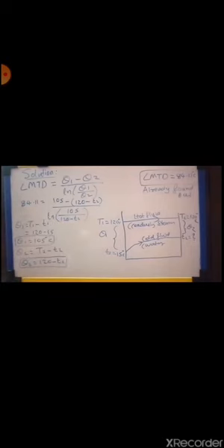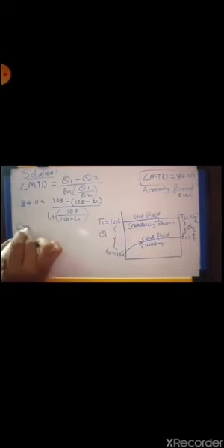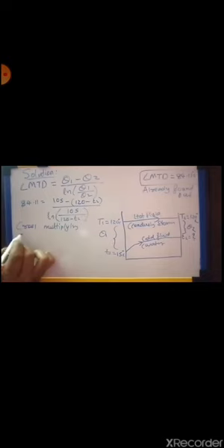Then the next step is cross multiplying. Cross multiplying, we get ln of 105 divided by (120 minus t2) into 84.11 is equal to 105 minus (120 minus t2). While solving this, we get the value for t2 as 56 degrees centigrade. Okay, this is the answer.